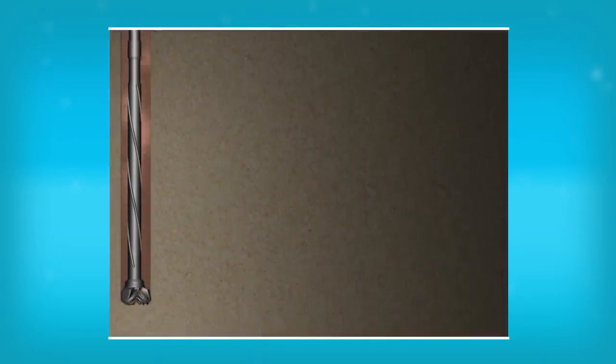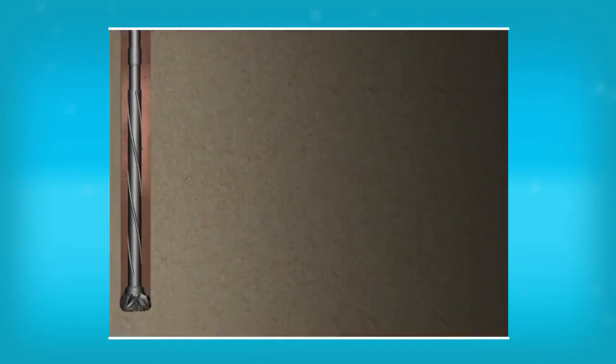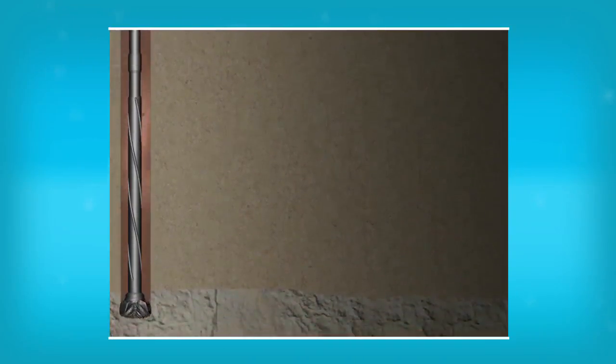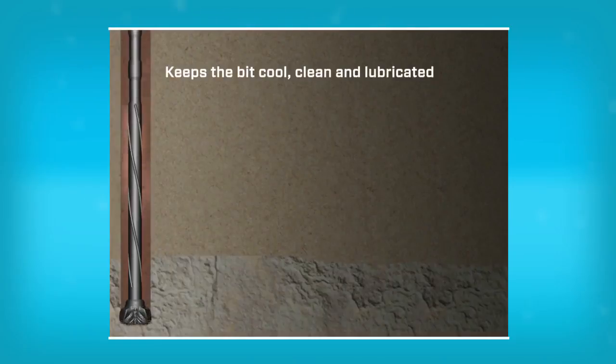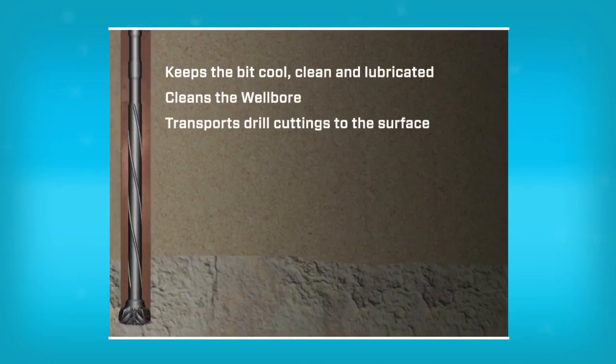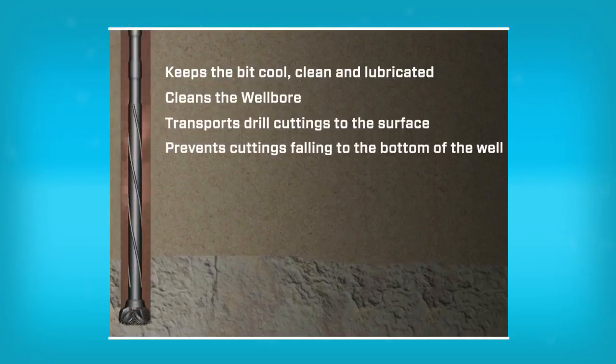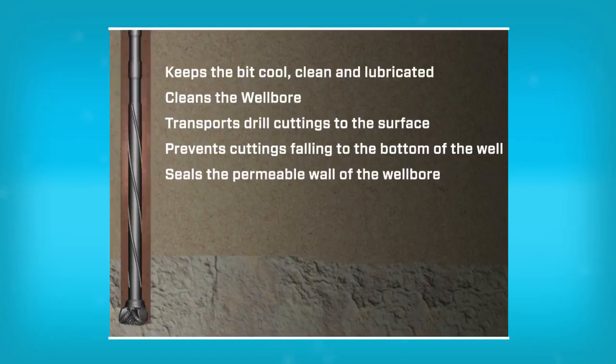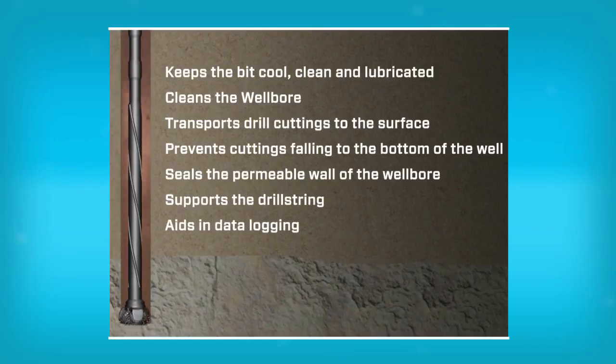Drilling fluid, also known as drilling mud, is very important for drilling wells and serves a multitude of purposes. Drilling fluid is used to keep the drill bit clean, lubricated and cool while drilling. It cleans the wellbore, transports the drilled cuttings back to surface, prevents the cuttings from falling back to the bottom of the well, seals the permeable wall of the wellbore when it solidifies to produce a filter cake, helps to support the drill string. Data loggers use the properties of the mud to monitor the drilling process using specialized tools.